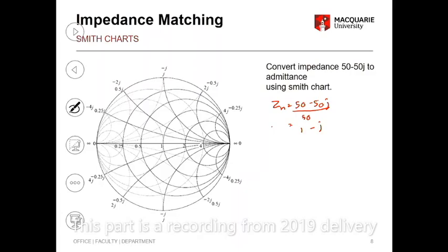So I'm on the impedance Smith chart, which is the darker lines, not the dotted lines. So there are dotted lines, visible enough, yeah. So I'm in this resistive circle somewhere, that's 1, and I'm in minus J. So minus J is this reactance curve.